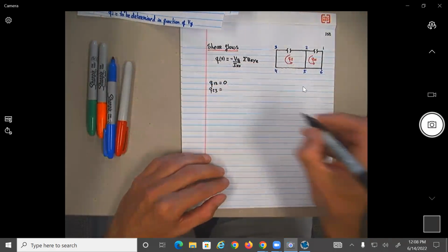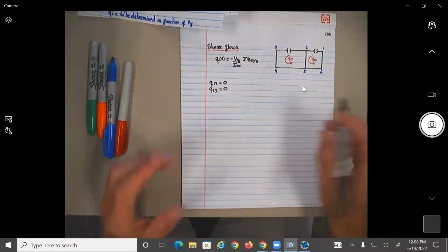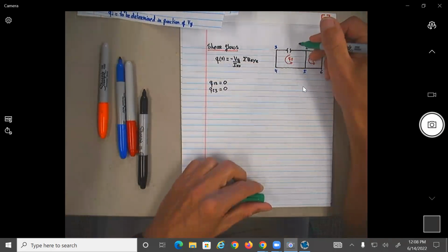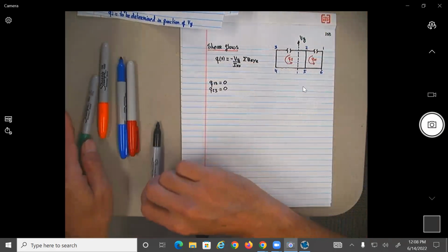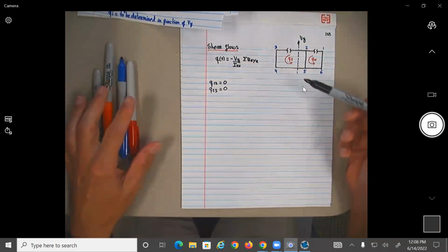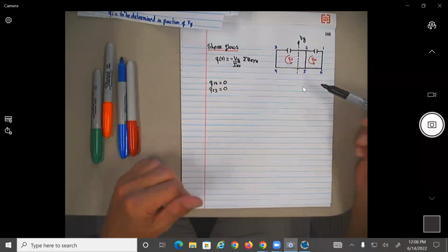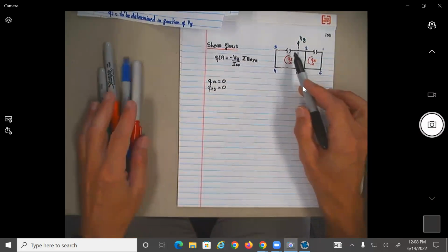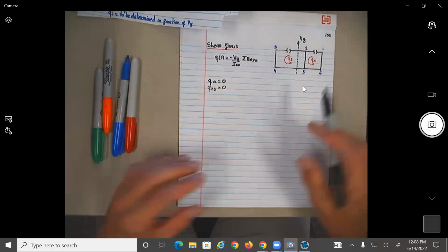What would be Q23? 0, there is a cut. Okay, now I'm going to put something. I know this stuff, we can make it very quick, but this is not that important for this figure, just for the understanding. Now that we do this, which ones should be the elements that carry a load? It should only be 3, 4, 2, 5, and 1, 6, no? All the other ones should be 0. So that also helps us to validate. So this should be 0, this is 0. Then you can do by symmetry 0 and 0, but let's see what the math is going to give us.